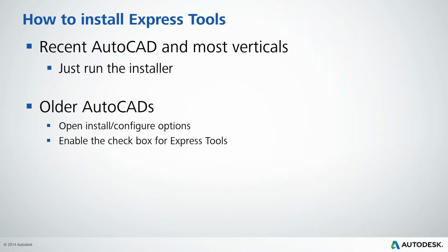And you just got to go back into the installer again, run it, and do add or modify features and add that back in. So if you have AutoCAD LT, sorry to say, but the Express Tools are not available. And that's because many of these tools are still built using AutoLISP and things, which is not available within AutoCAD LT. The good news there is that a lot of the Express Tools that were in the product have actually migrated into AutoCAD and AutoCAD LT directly. So there's a lot more of what used to be Express Tools in the past actually in the product.